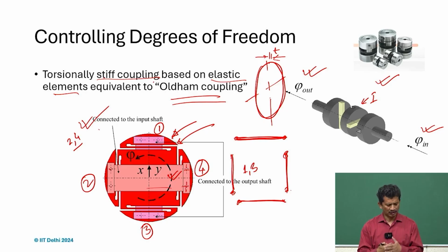So, if we design it using the concepts we study in design of machine elements, and take care of the fatigue and all those things if it is a dynamic application, we realize that we do not even need to remove or service these parts. Moreover, if we are looking for some application in vacuum or in space and we need to couple, we can easily get rid of any traditional old-time coupling and go for a flexible coupling. That is the biggest advantage we can have.